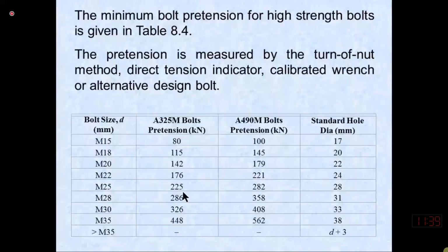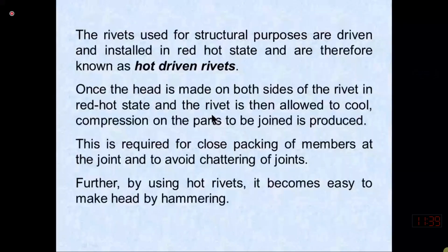The ASTM specification A502 deals with this type of rivet and qualifies these rivets as grade 1, grade 2, and grade 3. So we have three types of rivet. I am checking if any table is available in the LRFD manual where the properties of these fasteners are given.